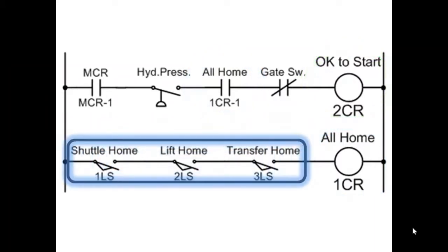Now here's our three limit switches. Limit switches open and close by mechanical contact. By the way, they're always drawn in the normal position and they're normally open. They are held open by a spring, and they have a little arm or a roller probe that sticks out, and when they make physical contact with something, it depresses the mechanical device and closes the switch. If the mechanical contact moves away, then the switch is pulled back open by the spring.